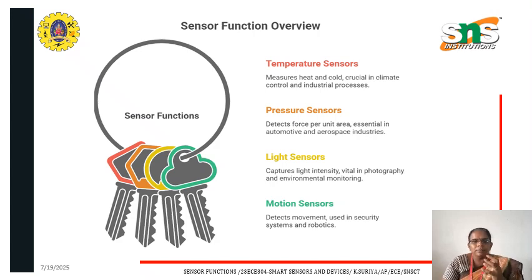A temperature sensor measures the heat or temperature changes. For example, thermocouples and thermistors, where a thermocouple converts the temperature into a voltage. A thermistor detects the changes in the resistance with the temperature. It is used in weather monitoring, medical thermometers, etc.